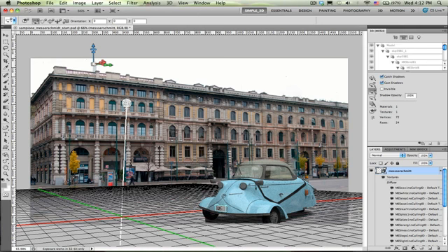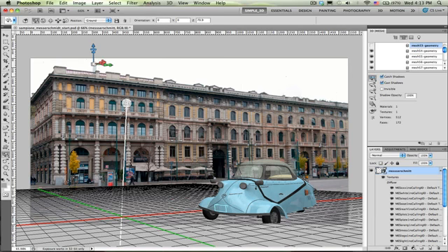So I'm going to click on that license plate, and again, if I rotate this, you can see I'm changing the position of this, but I actually want to identify where it is in the scene graph and hide it. Notice that every mesh and material has a nice eyeball icon on the left, very familiar to Photoshop users, where I can click on that and hide it. Okay, I'm going to do that again because there's actually 2 meshes associated there, and find it in the scene graph, there it is, and hide that. And you can see that I've just turned that mesh off, which is pretty nice.